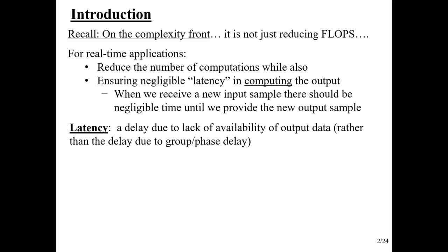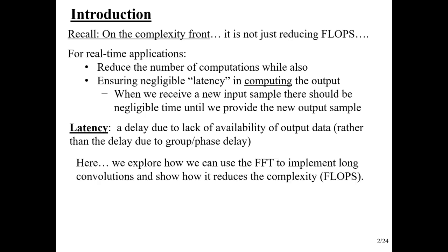The group and phase delay is a delay in the filter, or in the input to output, due to phase shifts. But that's not what this is. This is we have a bunch of data that's coming in, and we can't compute the output now without some delay. That would be a latency.